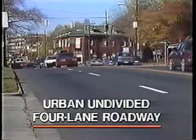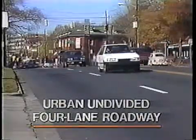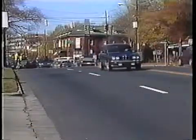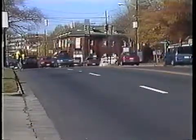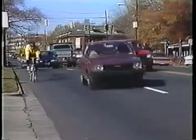The next example is an urban undivided 4-lane roadway. The work being done makes it necessary to close the right lane of the roadway. If the left lane were to be closed, the layout would be reversed.